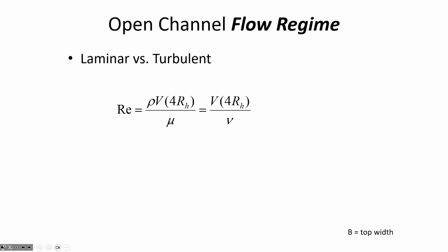Will we be looking at backwater in capacity? We will. And water surface slope is a different thing. For the channel slope, when we're working with steady uniform flow, we're just always going to have downhill as positive slope.